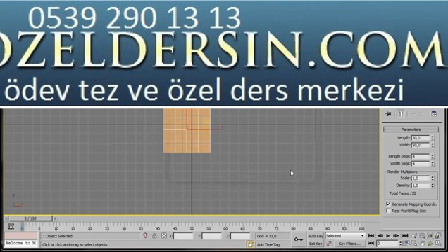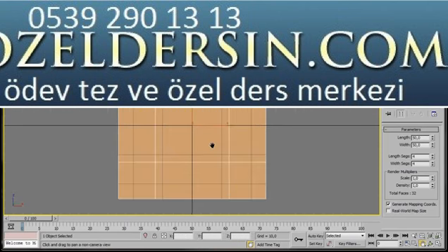Okay, now we're going to select the Select and Move tool. I'm going to drop right down to the bottom to the Transform dials. Now we can right click on the bottom spinners to bring them back to 0. This will center the object to the center of the grid. Now with the plane still selected, press Z on the keyboard to zoom in.